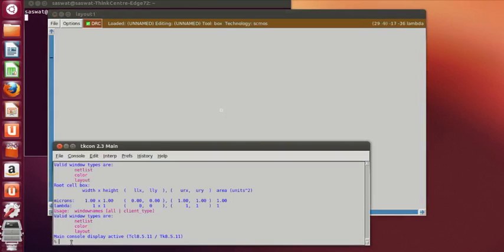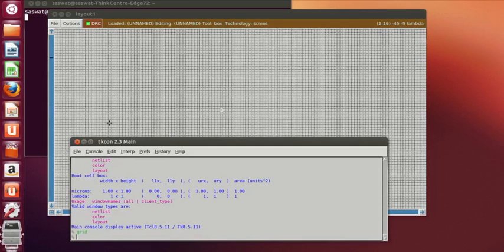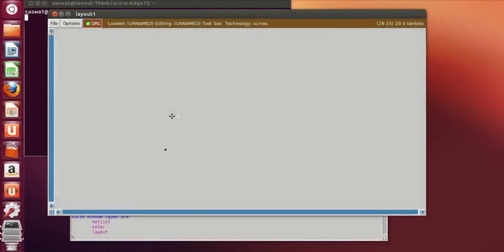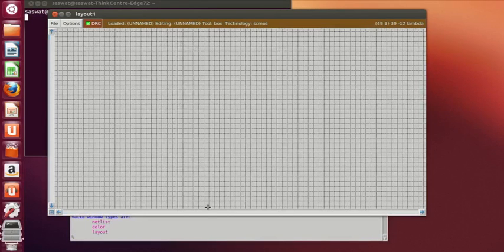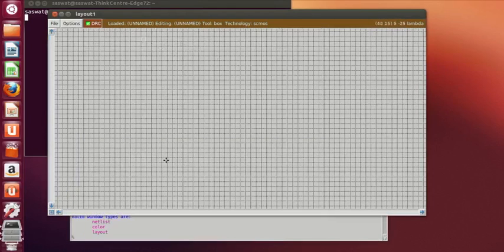Now we have to grid in. So type grid. So now you can see the small boxes. Shift Z to zoom out, Z to zoom in. Now at first we have to draw the NAND part and then the inverter part in order to obtain the 2-input AND gate.